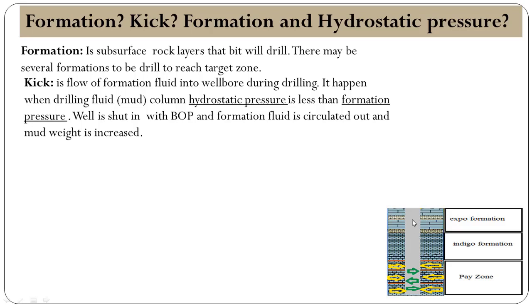This is the wellbore and it has the drilling mud or drilling fluid that must have pressure greater than the formation pressure to sustain the pressure inside the rock. If the hydrostatic pressure of the wellbore decreases due to any reason, then the formation pressure, in this case the formation fluid, will start entering into the wellbore. This phenomenon is called kick.